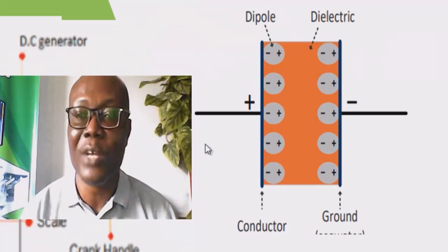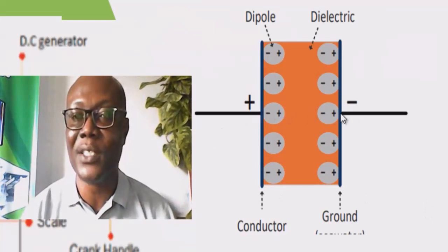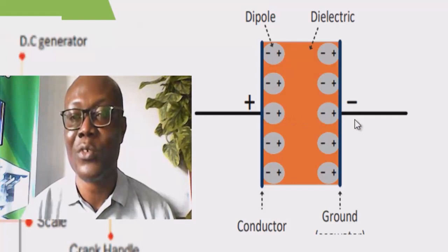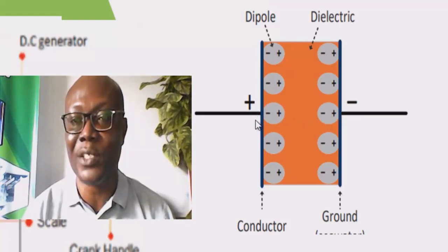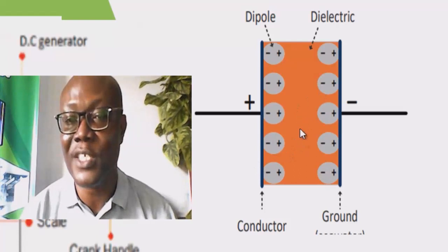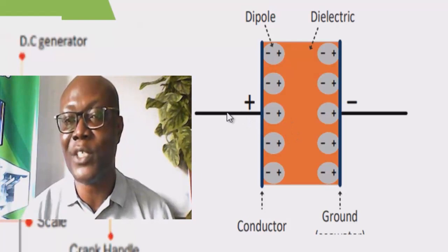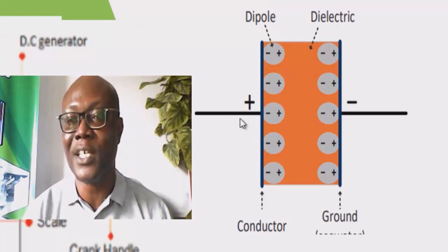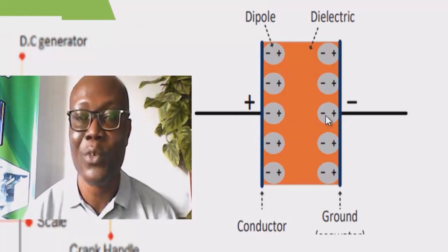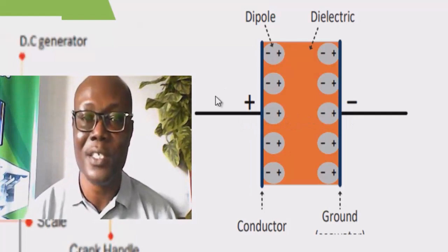So this is what you are actually doing, subjecting both ends of the insulator to a voltage difference. Remember, what you are injecting is a DC voltage. So you cause realignment of these dipoles. Insulation resistance will be gotten from dividing the voltage that you applied by the leakage current that will flow in the circuit.